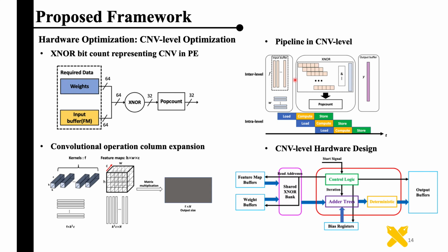Conventionally, the feature map's dimension and kernel dimension are quite different. If we transform these matrices into a data stream, we need to load almost the whole feature map, which may again challenge the resources on board. Since the addition is just an operation of pop count, as long as the vectors correspond to the unrolling order in the kernel, the order of the columns will not affect the output result. Here we show the data flow on board, to further clarify our implementation.